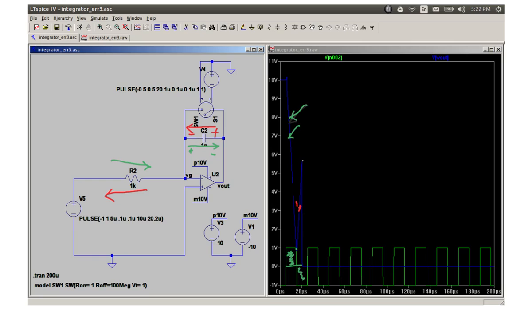And then suddenly at this point the voltage is still negative, so it should have continued going, like that up, but it's sort of dying, which means it is getting connected to ground. The input voltage is at ground, so the output voltage is also going at ground. Hmm. Well, the capacitor can't do that. The only thing that can do that is a switch. If I short this node from here to here, well, okay, that makes sense, because initially I was supposed to have a switch that held this voltage at ground and then released it, but now the opposite is happening. So this voltage source is flipped around.